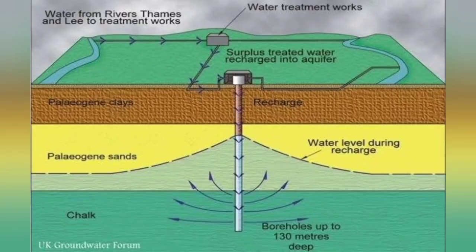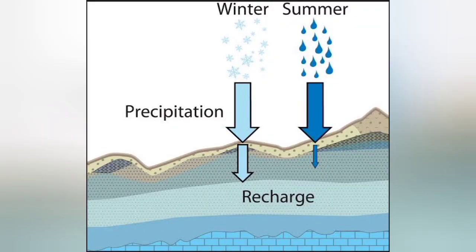hydrometeorological studies. These are taken generally to decipher the rainfall pattern, evaporation losses, and climatological features. These can bring out the extent of evaporation losses in the post monsoon period, which would be helpful in designing the storages of any particular capacity with a view to have minimum evaporation losses.